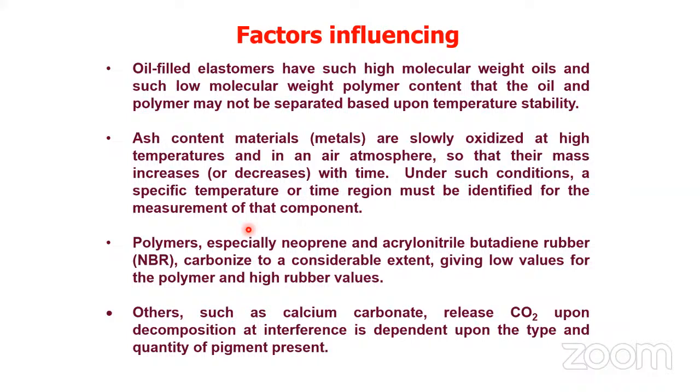Then we started with some advanced techniques like DSC, differential scanning calorimeter, by which we can identify thermal transitions of your polymeric material: glass transition temperature, melting points, crystallinity regions, heat flow, and heat capacity of polymeric materials, that we can identify using DSC, or differential scanning calorimeter. Okay.